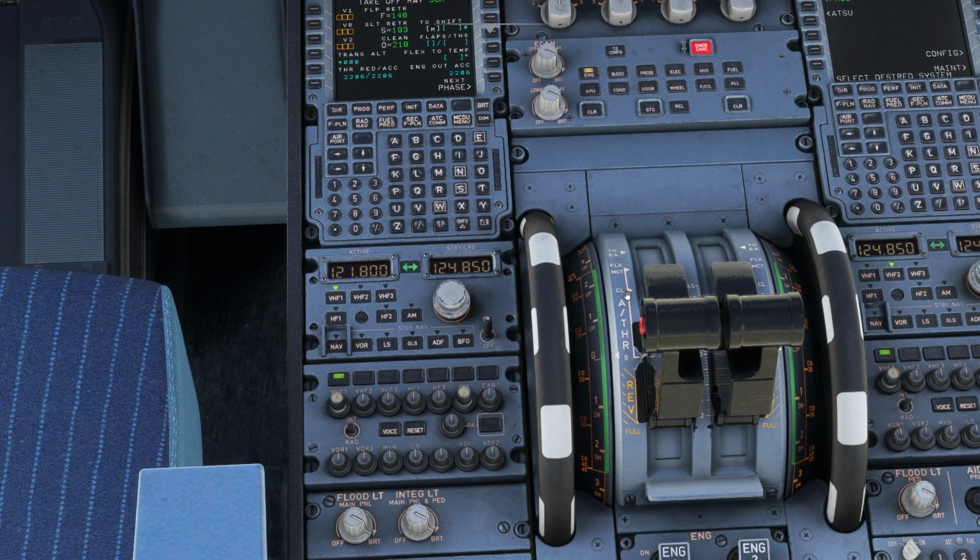During the flight phase, right after the takeoff, the throttle is moved from flex or TOGA to climb, because it's a reduced thrust, as the plane cannot fly the whole flight with the maximum thrust. So the thrust is reduced in order to have less stress on the engines and to increase the engine's life. So you set this throttle to climb, and then because of the auto throttle, the autopilot keeps on increasing or decreasing the power given to the engines.